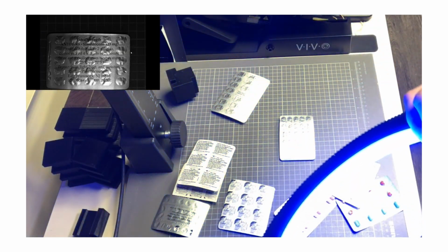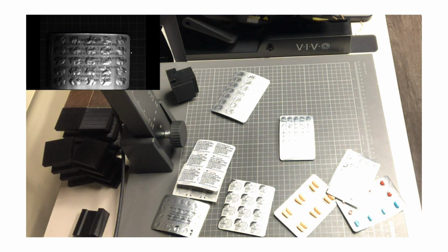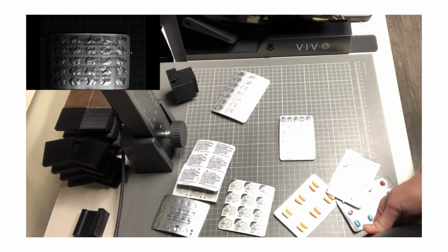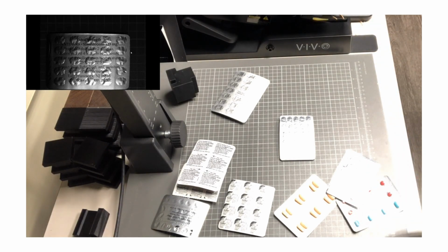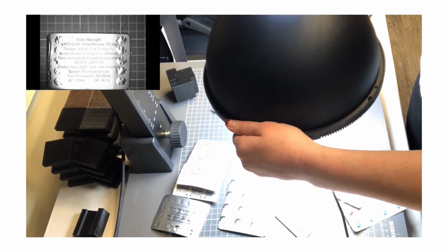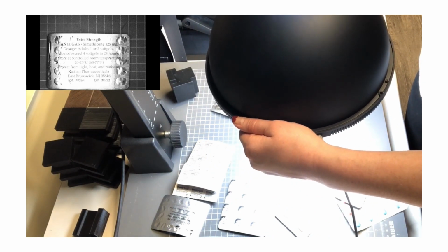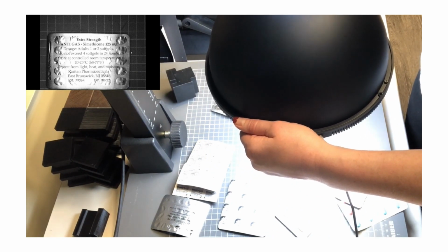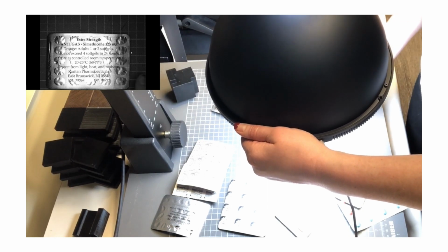So knowing that we want bright field, knowing that direct light is going to cause glare and issues, we step forward to the light that we know removes 3D texture, which is a dome light. So I can take my dome light, turn it on, and I hold it over my sample. And the image here still isn't great. It's better in the middle, but we're still getting that drop off at the end.